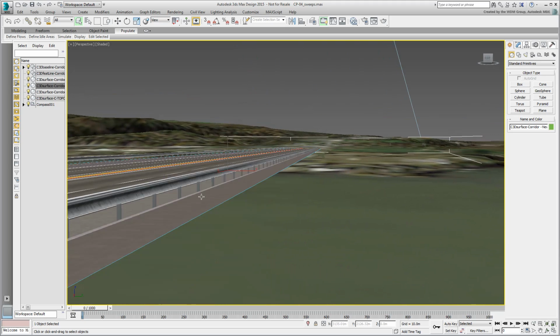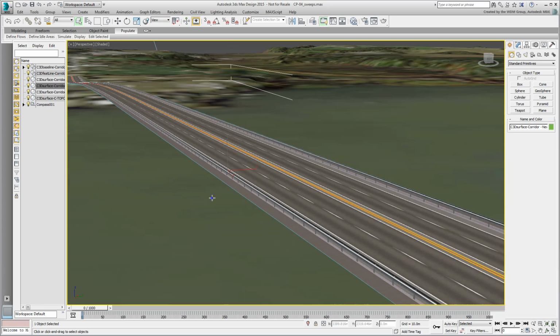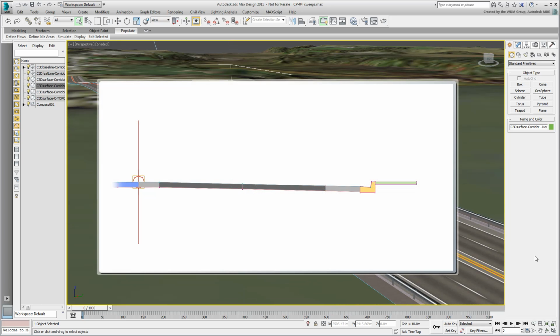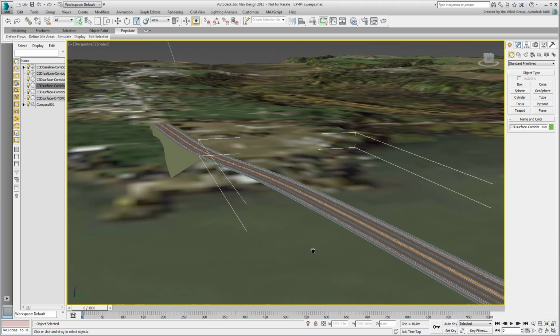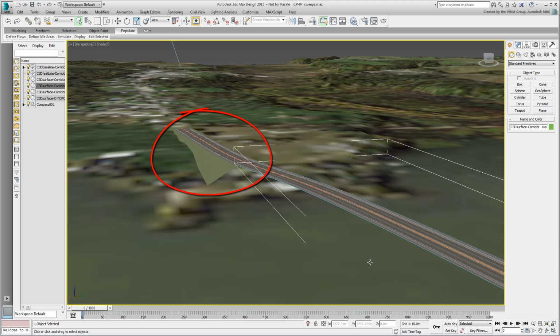There's absolutely no depth to the bridge as it currently stands. The existing geometry is based on a cross-section that only covers the top of the bridge. In fact, you need another cross-section that includes the side protections, walls, fences, but also the underside of the bridge. You only need that for the part over the water. The bridge ends have sloped areas courtesy of the Civil 3D daylight subassemblies.